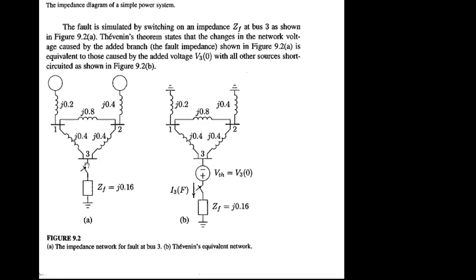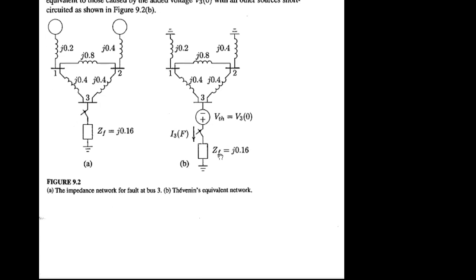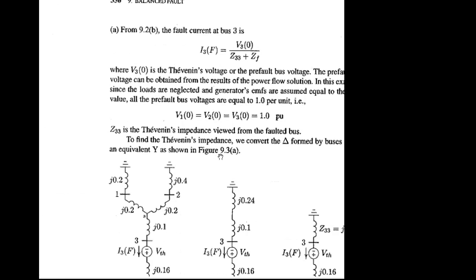Okay, if it is okay, we can replace that drawing with the Thevenin circuit, Thevenin voltage, and the impedance is there to address that fault current through this path in terms of bus 3 fault. So as we know, bus fault can be managed by the impedance for that particular node and the fault impedance together. Is it okay?